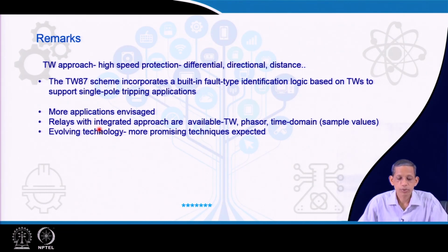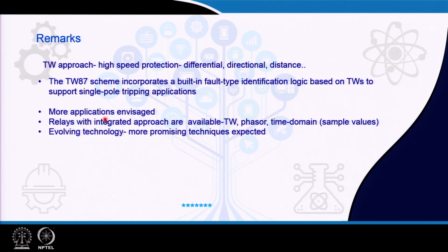Relays with an integrated approach are available: travelling wave, phasor, time domain and so on. In case the travelling wave signal is not available because of low signal strength for certain switching instants, the relay should also incorporate phasor, and there are other reasons to support that, including the time domain approach based on sample values. So, this technology is evolving and more promising techniques and principles are expected in the near future.